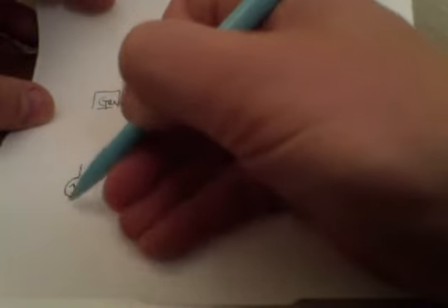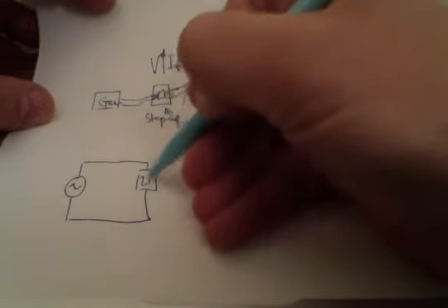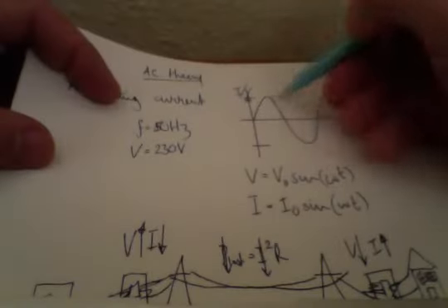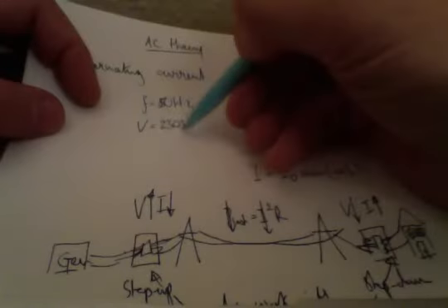So that means, coming back, our circuits run with AC. I'm going to do a basic circuit here, and there you go. Let's say I've got 2 ohms running there, and I have 10 volts AC. And I say 10 volts, let's call it equivalent, because we know that obviously the voltage and the current is varying, but we're quite happy in describing in our homes that we have 230 volts equivalent coming through.